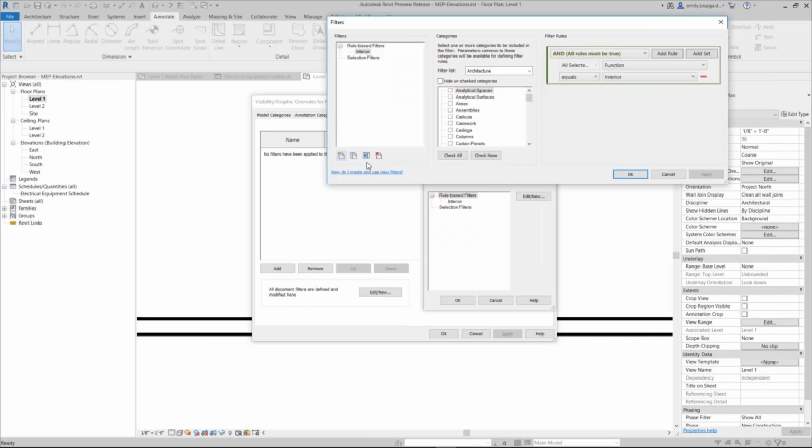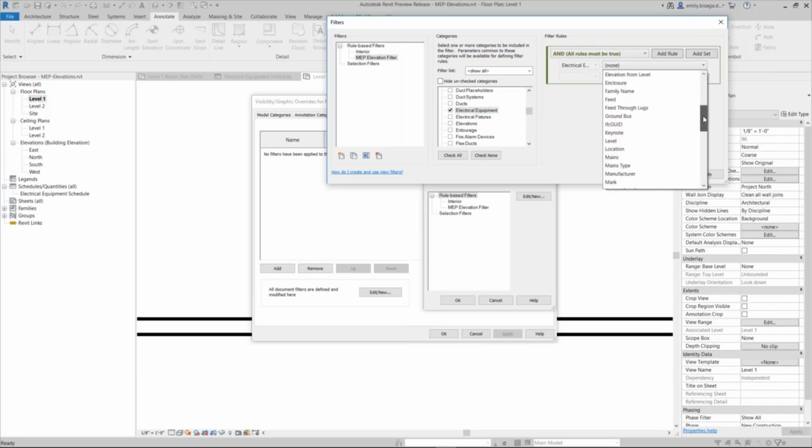Now if I want to have a filter, I can use the filter, say all the tags which are above 3 feet, show me and change the colors to red so that I can identify in my whole drawing which electrical panels are kept at 3 feet elevation. So I select that, and there you can see I have an elevation level. I set it to greater than 2 feet, apply, okay, and make them show in a thick red color. Now you can see in the entire drawing which electrical panels are at the 3 feet level.